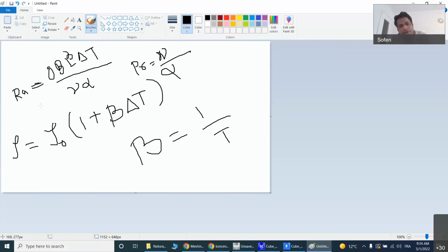Now, what dimensions have you already fixed? Suppose you fix the fluid, meaning Prandtl number 0.71, the fluid is air at a particular reference temperature. Then this nu and alpha become constants. You cannot change them over here, right? For turbulent flow, you put the Rayleigh number as 10 to the power 8. Nu into alpha are also constant. You can get the value of nu into alpha from the table at a reference temperature, 30, 40, whatever temperature you put as reference. At that temperature, you can determine nu into alpha.